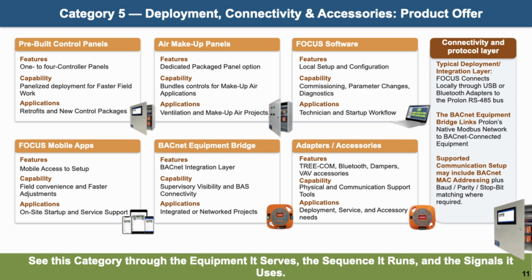Depending on the setup, supported communication parameters may include BACnet MAC addressing plus baud rate, parity, and stop bit matching. The main idea is that deployment is not limited to physical hardware. It also includes how technicians connect, configure, commission, troubleshoot, and expose the system to other building-level control layers.